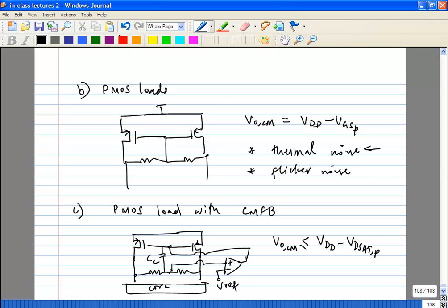How about flicker noise? Let's say we are looking at down conversion mixers. Up conversion mixers, we know we have a tuned load. So in a down conversion mixer, we down convert to IF, and if the IF is large enough, you don't worry about flicker noise, because the flicker noise is going to be around baseband.